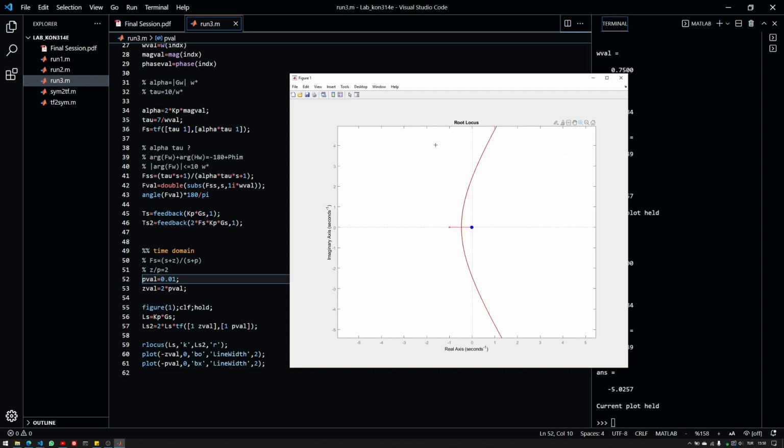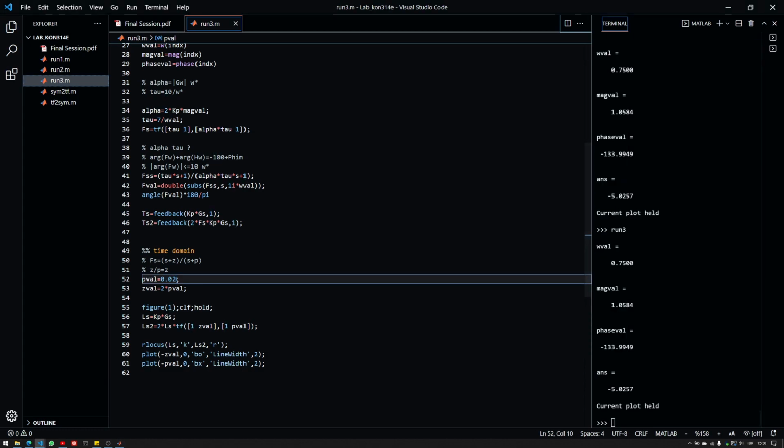And you can see I have directly matched them. So the previous root locus and the root locus now is almost the same. But I have a pole zero cancellation near the origin, so I should be basically a bit safer than this. It's not really safe to add a pole and a zero